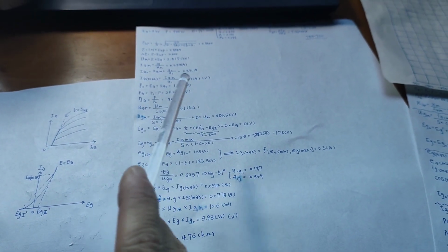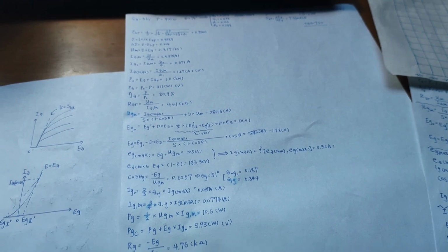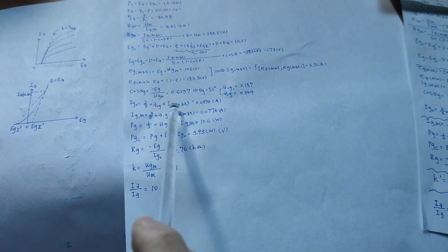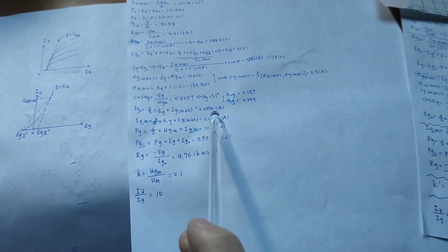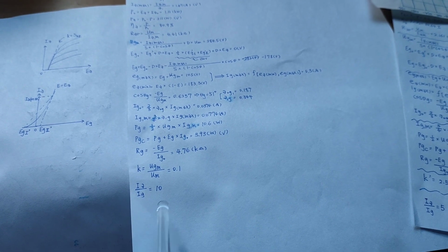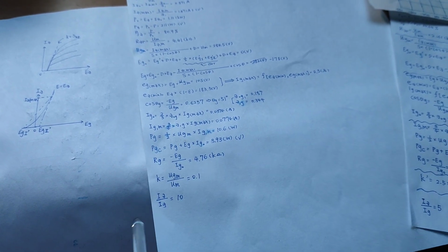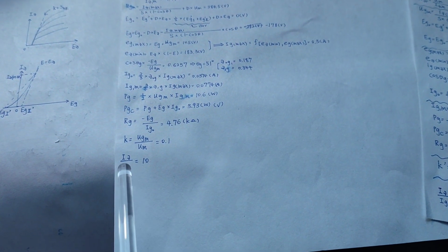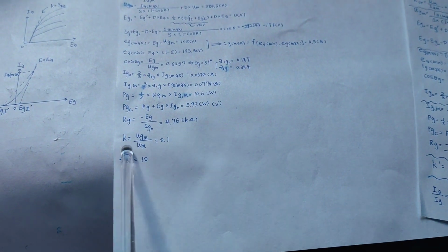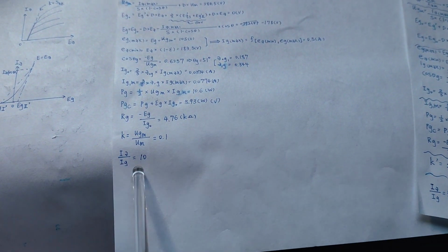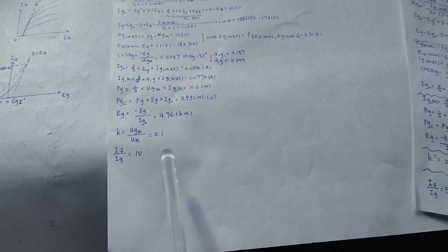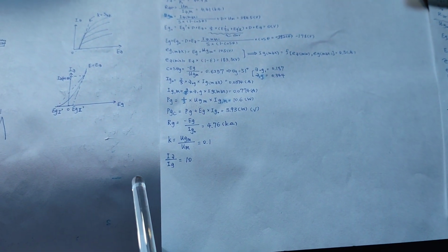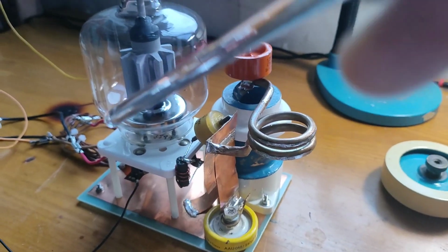anode current, which you can also see as the cathode current. And you need to also check your grid DC voltage, which is this one. And you can check the ratio between these two values when you have just finished your calculation. Normally for a thoriated tungsten filament vacuum tube, this value should be around 10% to 25%. Remember that, 10 to 25%. And that's just for that.